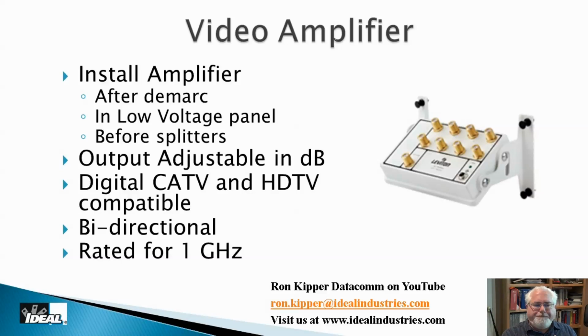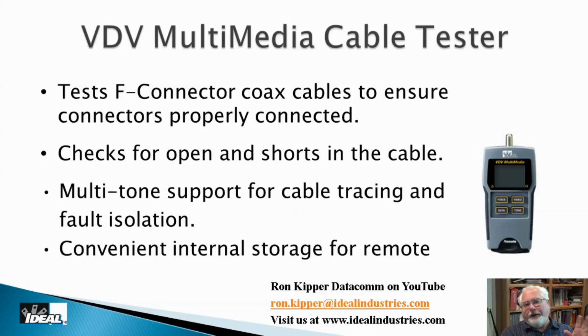Okay. When we go to test coax, as a general rule, all we test in the cable is for opens and shorts. Here's an example of what we call our voice data video testers, or VDV as we call it. It just tests for opens and shorts in coaxial cables. If you want something that measures signal strength, that's a lot more money. You're going to spend several hundred dollars on something that might be able to measure the signal strength at the low end of the frequency, but it can't measure the signal strength at the higher frequencies. Those are a lot more money.